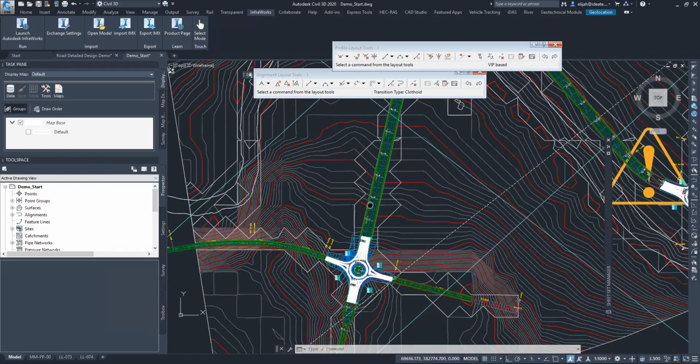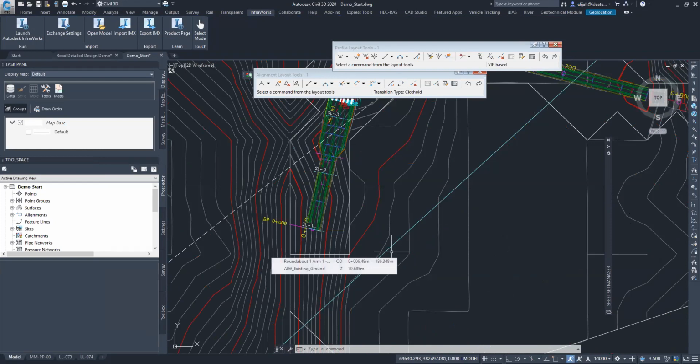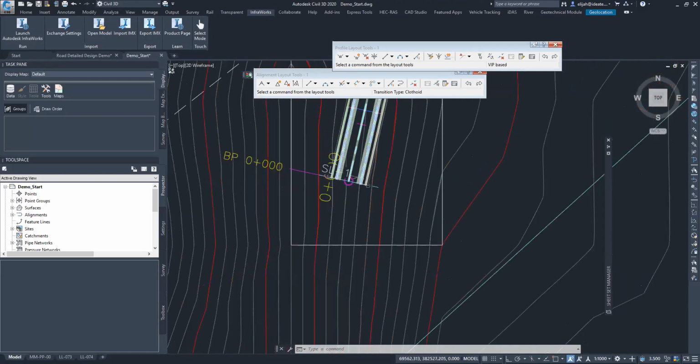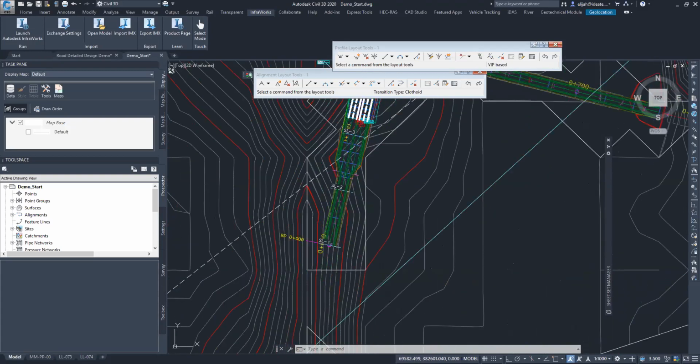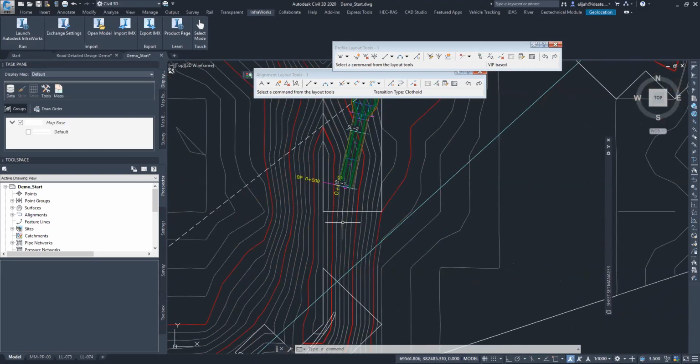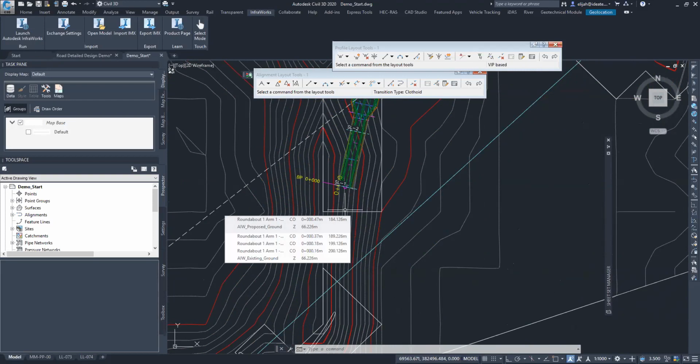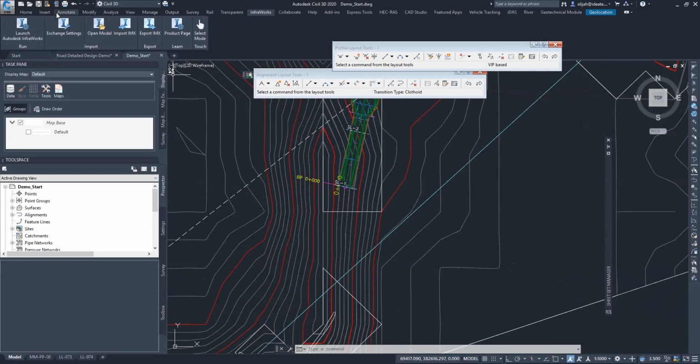So to do that, you basically require what we call a control point. So control point or a benchmark is basically the reference point that the surveyor will be using on site to be able to stake out the geometry of the road. So like I have the center line of the road, which basically will be guiding the path that the road should follow. But when staking it out or when laying it out, what should be the control point within the field? So basically that should be defined and agreed on, and the client, in many cases a road agency, should confirm that the control point is correctly defined and correct accuracy being applied.